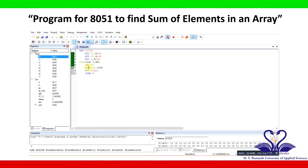So 05 will be decremented in this step. So it becomes 04. It will check whether it is 0 or not. So it is not 0, so the condition is true. That is why, as R1 is not 0, it goes back to this loop. Then again these steps get executed.